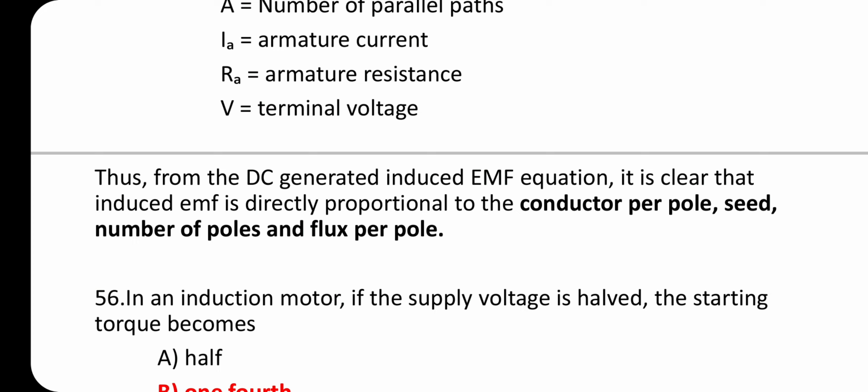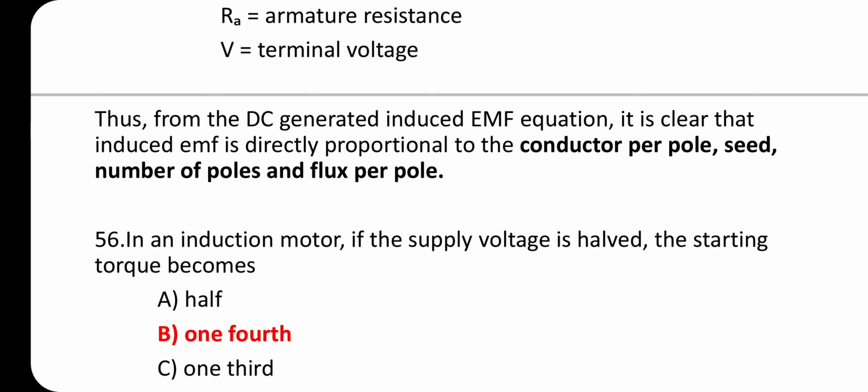Thus, from the DC generator induced EMF equation, it is clear that induced EMF is directly proportional to the number of conductors, speed, number of poles and flux per pole.